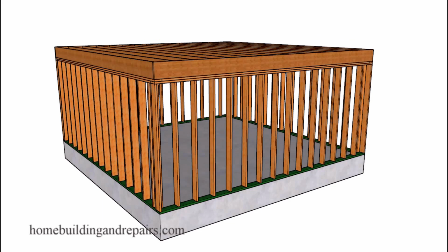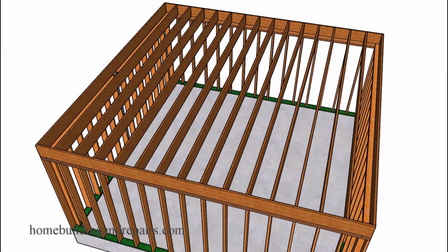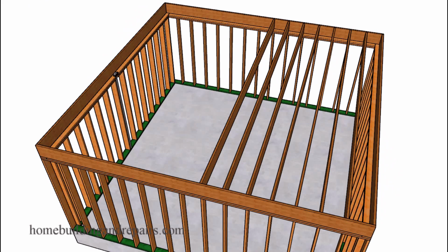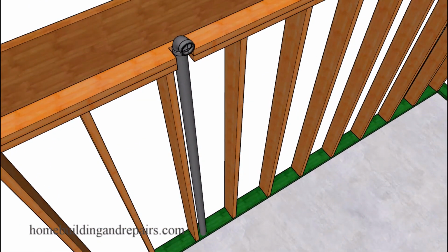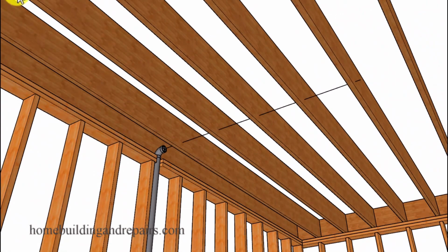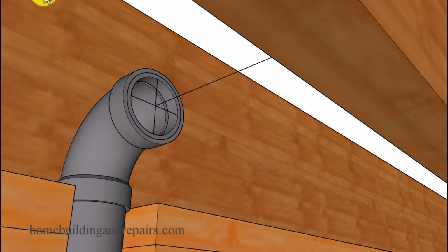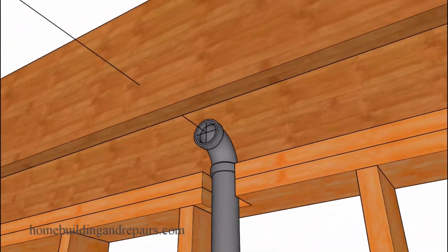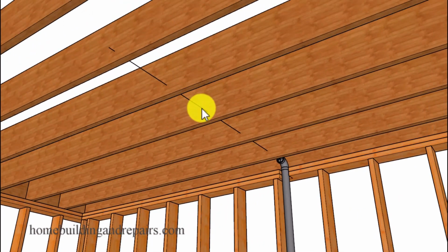In this video, I will provide you with an easier way to locate the plumbing drain pipe holes. This might even be able to be used for your vent pipes, anything that's going to be at an angle. And for the most part, if your joists are spaced equally, 16 inches on center, for example, then you could calculate the distance for each floor joist that the line would need to raise.